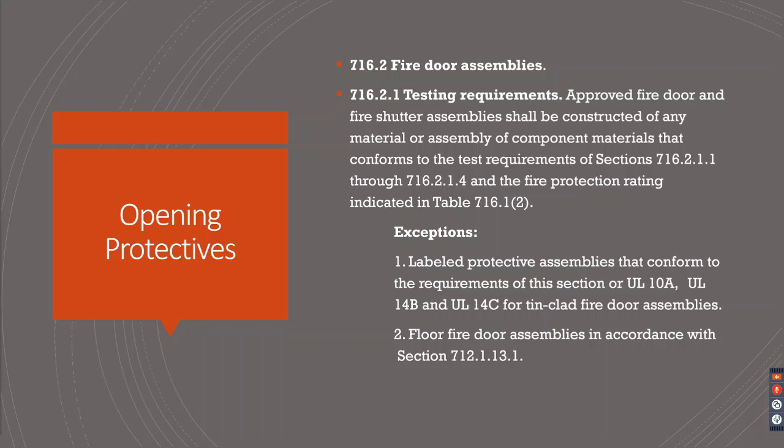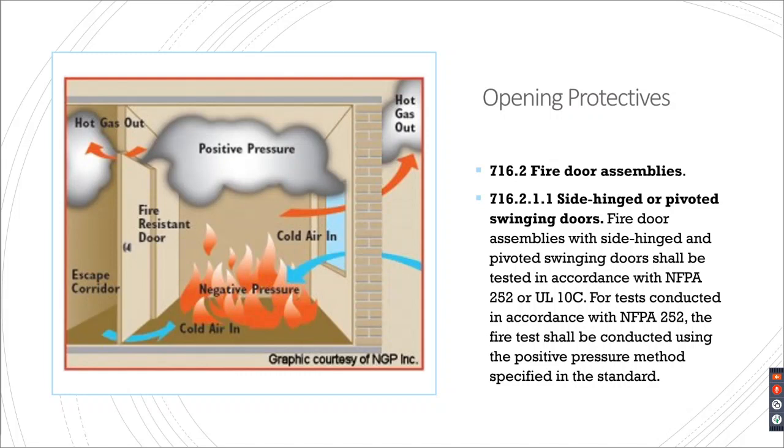If you've got a fire door assembly in your floor, they have their own specific requirements because, of course, it's going to be tested differently, right? A door that you're walking through, room to room, as opposed to something like a hatch, where the heat is going to be up there, right? The heat's going right up to those, so floor fire door assemblies have their own requirements. So yes, I'm sorry, we did switch to fire doors. We moved from glazing to fire doors.